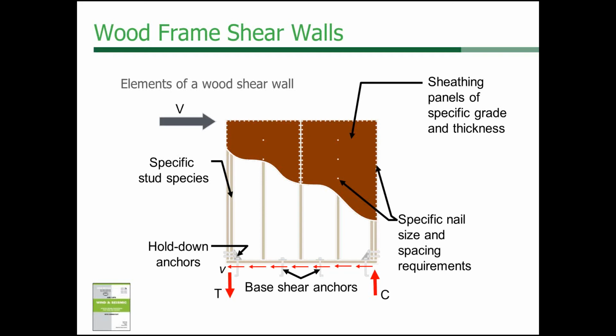Or even if it was at 2 inches on center, then you'd have 160 nails. Then imagine that you would have hundreds of feet of this. Say you have a 1,200 square foot house. If you extrapolate that, the nails of your shear walls, and then nails in your diaphragm, you could have 10,000 nails in your walls and floors and roof.